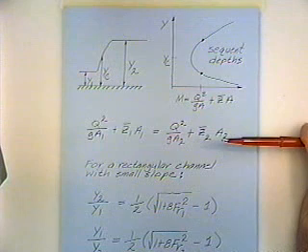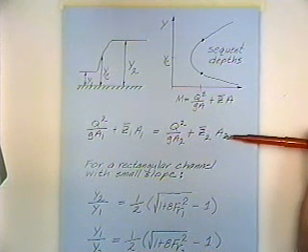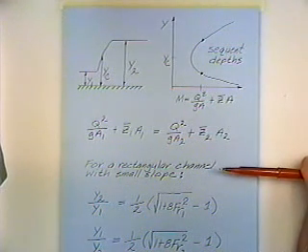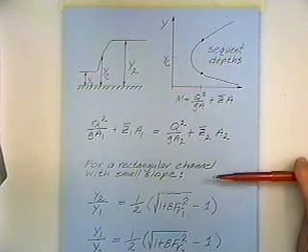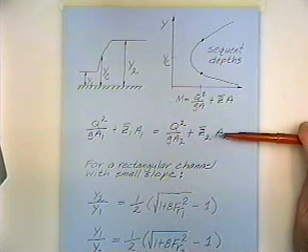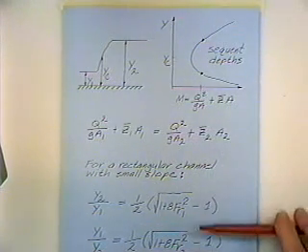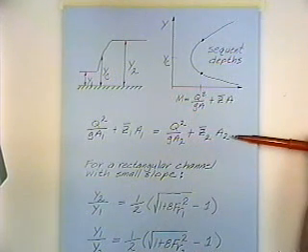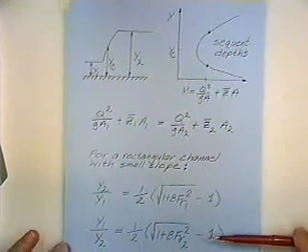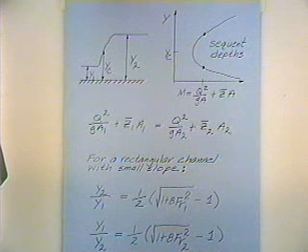Now, basic textbooks will continue the derivation, and whereas this equation is good for any type of geometry, if you have a simple case where you've got a rectangular channel with a small slope, you can take the basic equation, which is conservation of specific momentum, and go through some derivations and come up with these equations. So this is a general equation that's good for any geometry. These equations express the same concept, but they're only good for a rectangular channel. And it's got to be a small slope.